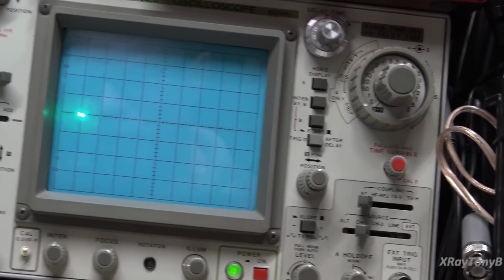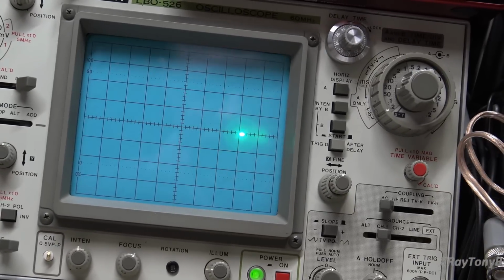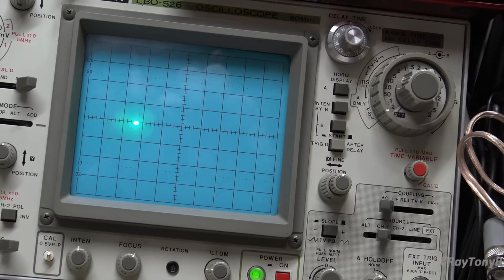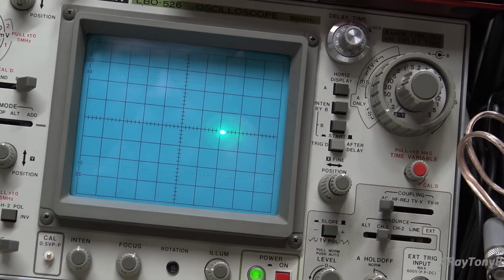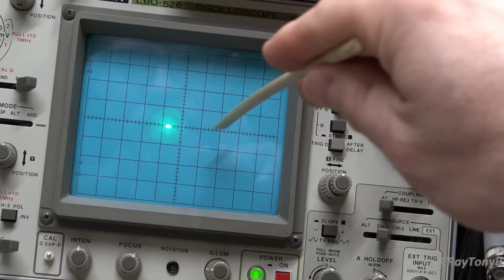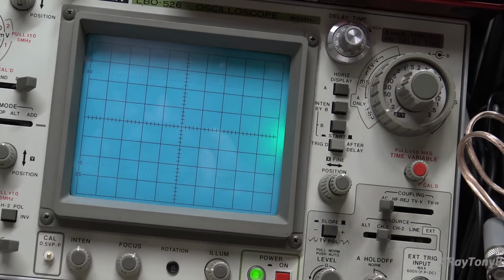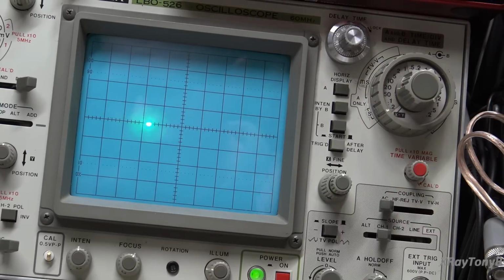Okay, we have our old analog oscilloscope connected up now. And what you see, this is called the trace. It's a little dot that's being projected onto the screen. All right? And it has a little amplifier connected in there. Right now it's sitting at 0 volts. This line across the middle represents 0 volts. So when there's no voltage in there, that little dot will just keep floating back and forth across here.